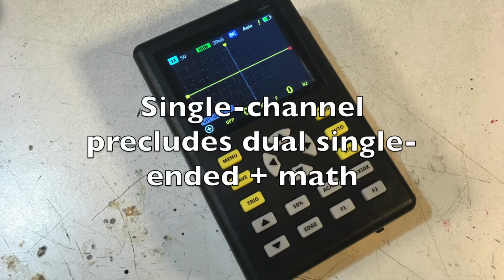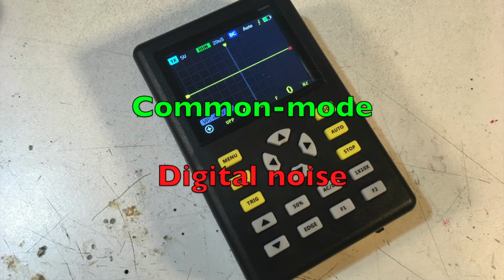And again, since we are single channel, that precludes taking the two single-ended channels, channel 1 and channel 2, running them in parallel single-ended mode and inverting one of them to cut out the common mode noise. So that's not something that we have the possibility of doing. And when you're talking about an analog scope and using the dual channel invert one trick, you're canceling out all the noise that is common to the channels, whereas with a digital scope, you're canceling out the common mode noise, but the digital noise is additive. So you still have digital noise times 2, which is going to raise your noise floor. And if this is noisy because of the overclocked chip and some dithering in those final bits, then that would just make the situation worse. So I don't know how much more useful that would be regardless.